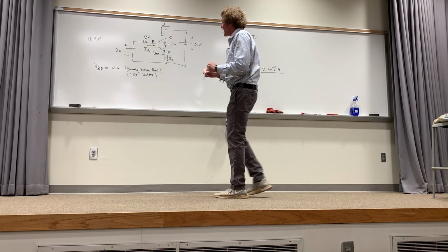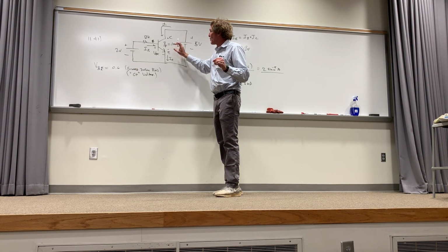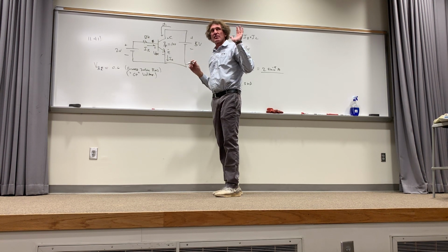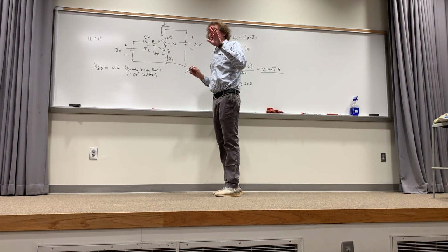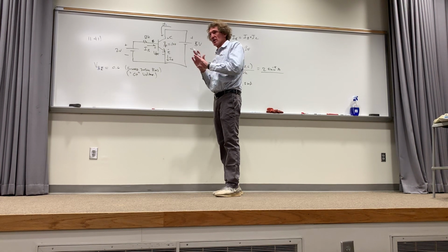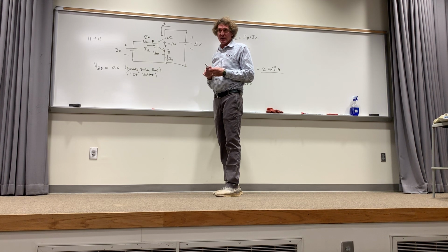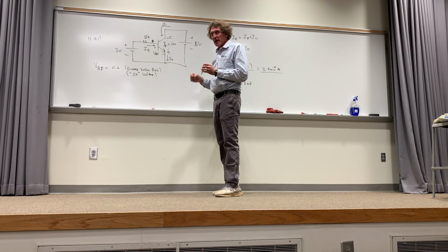Now, something I'll say, this voltage here, you have to have at least 0.1 volts from here to here for this to be in the active region. I'm not going to ask you about this, nor am I going to try to trick you on it. Remember, with these transistors, they can work in what's called the saturated mode or the active mode. This is active, where you get a linear amplification. Whatever current there, it's 100 times that there, if it's in a linear range, and that's what kind of problems you're going to get.